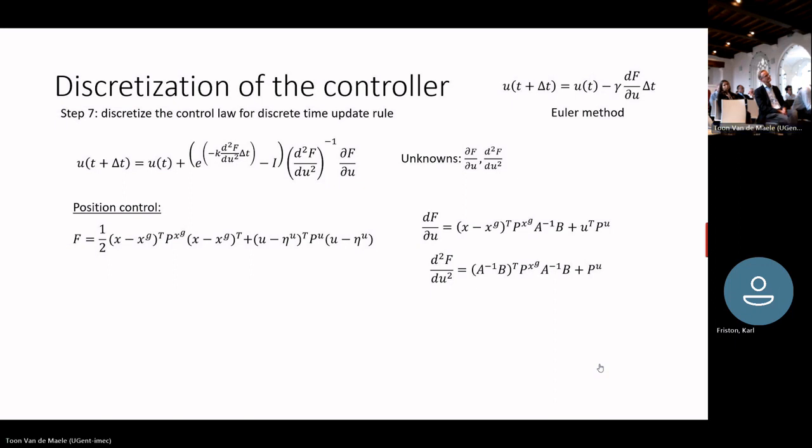So you can use any other discretization. I would highly prefer Runge-Kutta as well. Runge-Kutta is one of the strongest and widely used. It uses 4 or 5, as per the order. You can use trapezoidal methods as well. But I would recommend Runge-Kutta or this one for active inference problems. It always solves for me, so I'm pretty confident with it. That's why I put it here. But of course, feel free to use other discretization methods for the controller, but make sure that you use one.